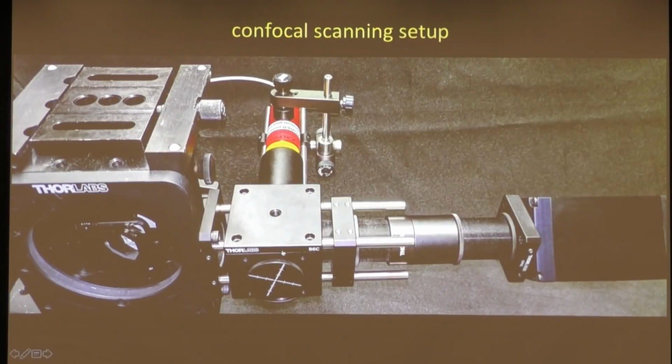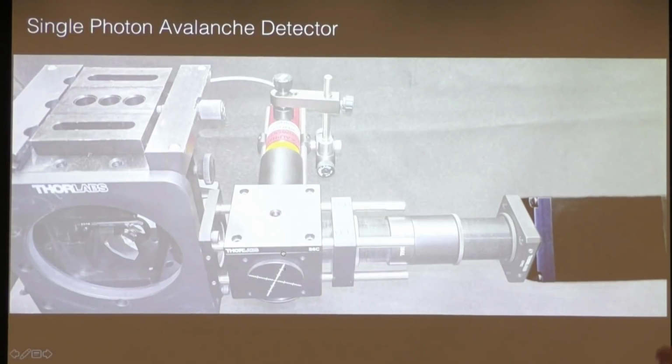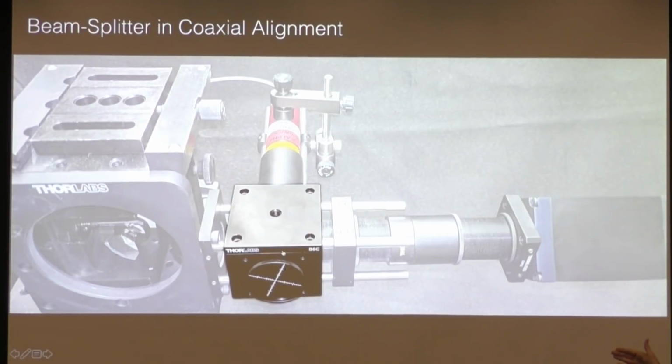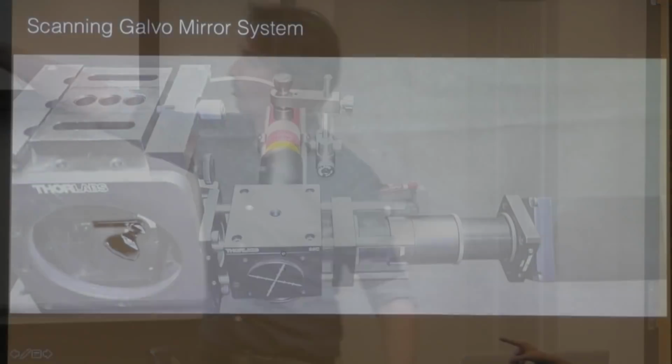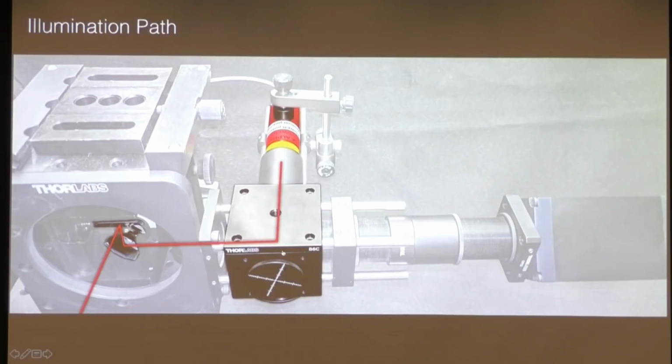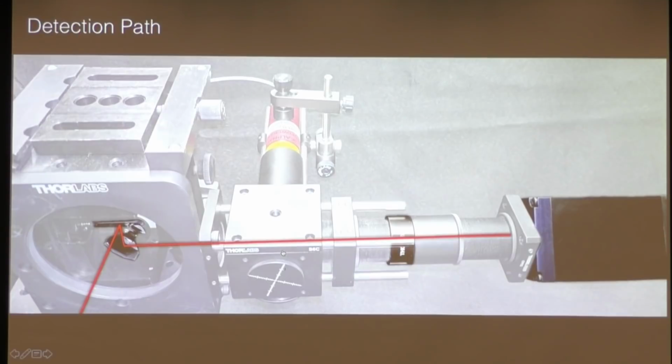And so we built this system that involves, again, a SPAD sensor here on the right. This is now a single pixel SPAD. And we have a lens that's placed in front. There's a pulsed laser, and they're aligned with a beam splitter. So basically, the laser and the sensor are illuminating and imaging the scene along the same ray. And we steer that ray with a pair of mirrors, Galvo mirrors, that allows us to scan basically a 2D patch along a wall. So our laser sends out these laser pulses out into the scene, and then we measure the light that comes back in response.